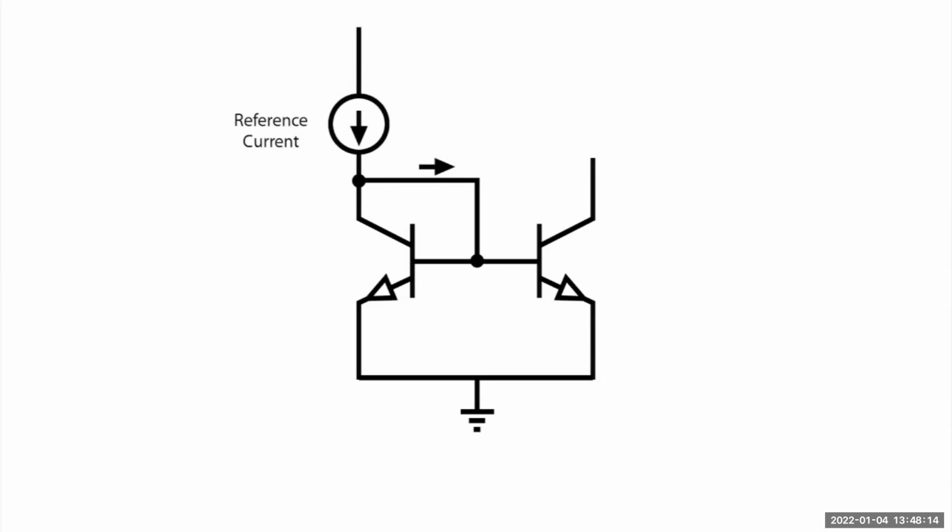A little bit of current flows to the base connection, and since we have identical transistors, the current is equally divided and injected into the bases. So the reference transistor turns on and lets some current pass through. Remember that the sum of twice the base current and the collector current is equal to the reference current that we want mirrored. The base current acting on the second transistor allows an almost equal amount of current to flow through it. This is how the current is mirrored.